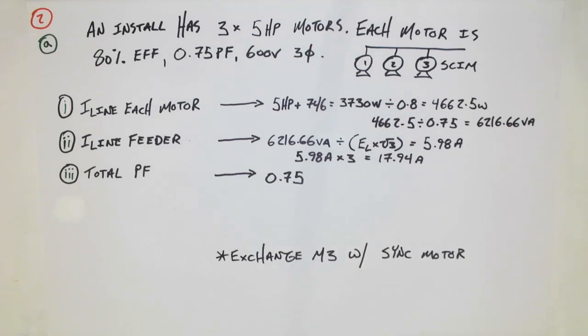Now to this installation, we're going to make a change, and we're going to exchange motor 3 with a synchronous motor. And what that's going to allow us to do is to power factor correct the 3 motors, or the feeder if you want to think of it that way. All right, well, let's take a look at how that's going to change things.